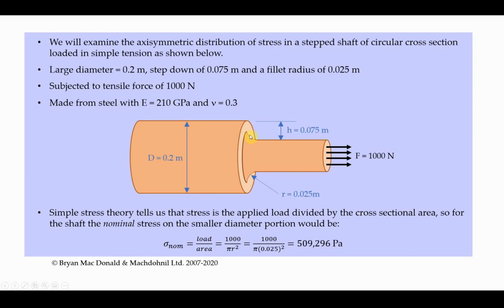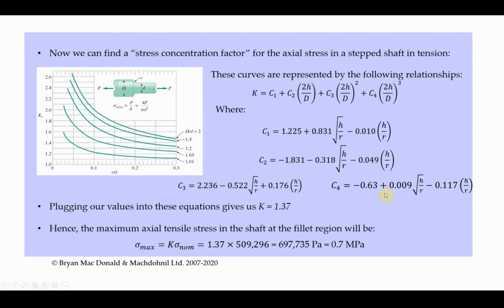So obviously we have a fillet here, and that fillet is a stress concentrator. So we're going to get a higher stress around this region where we have the change in area, and probably around the fillet here. So if we go and look up stress concentration factors, we can find a stress concentration factor for the axial stress in a stepped shaft in tension. So you get these curves here, if you look this up from a book of tables,